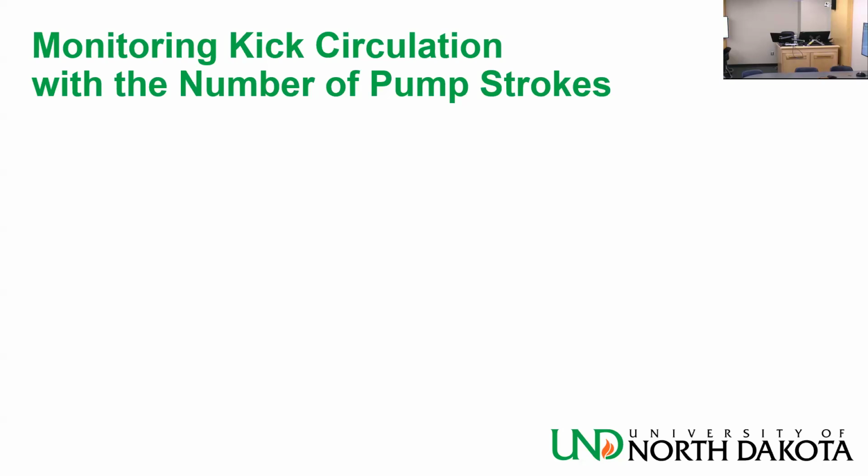From the pressure? No, not from the pressure. Something else that I can read on my screen. It's still not the pressures. I read the pressures, but how do I know? We said if we don't have any kick, then the pressures should be the same. But how do I know that the same holds when the kick is out of the well? How do I know I circulated enough to make it all the way up? I may see the same pressures, but I might be halfway. I might be using the wrong density.